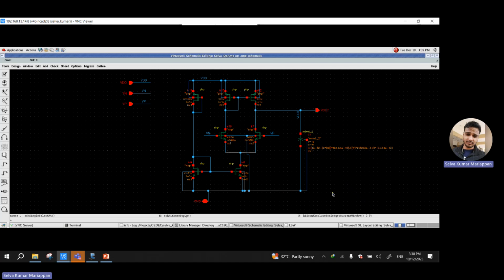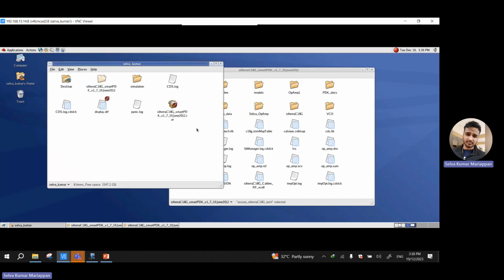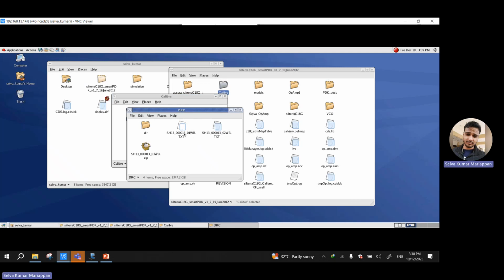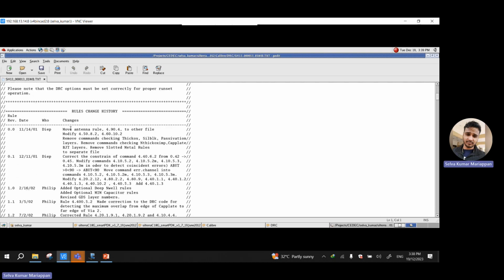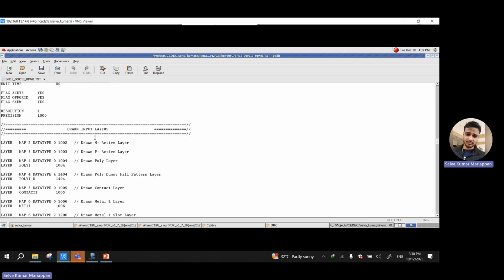You know why? Once you take components from other libraries, your DRC will have errors and your LVS won't pass, because it will see that the library does not match. Each of them actually comes from a rule file. You can check in your PDK, you will have the rule file actually. Like mine, I have my Calibre file here. Let me show you. DRC. So this is the rule file. See, there is generic. So you have all your rules stated here. I'm just showing an example here.